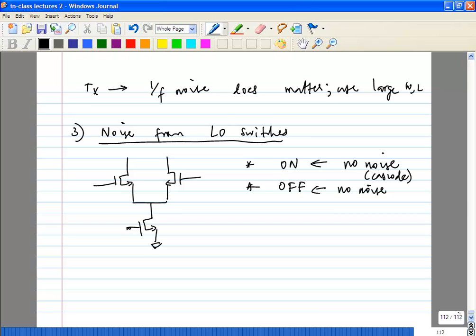So what we'll see is when they are switching, there are two sources of noise. One of them is called direct noise, which happens inherently due to the switching performance. The other one is indirect noise, which happens due to some kind of parasitic capacitances in the circuit. So in today's class, we'll just do the direct noise. I think most probably we won't even get to finish it. We'll continue next class. We'll finish off with indirect noise.